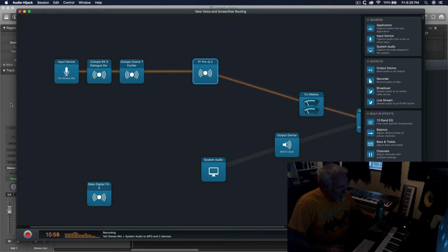So to get myself, the source, to be louder, I can either raise my voice like that, which starts creating different voice inflections, and not good noises come out when a person has to raise their voice, unless they're singing rock and roll, I guess. But if I move the mic closer, I don't have to talk as loud, and my voice gets quite loud. In fact, what that will allow me to do is turn down the mic gain.